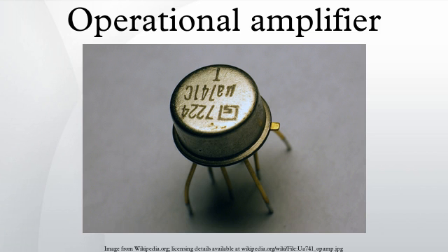On the other hand, a small positive change in voltage at the non-inverting input drives this transistor into conduction, reflected in an increase in current at the collector of Q3. This current drives Q7 further into conduction, which turns on current mirror Q5/Q6. Thus, the increase in Q3 emitter current is mirrored in an increase in Q6 collector current, resulting also in a decrease in base drive for Q15. Besides avoiding wasting 3 dB of gain here, this technique decreases common mode gain and feed-through of power supply noise.